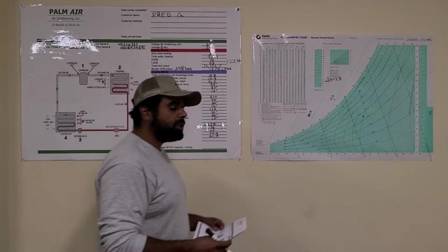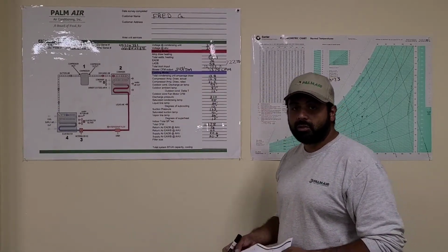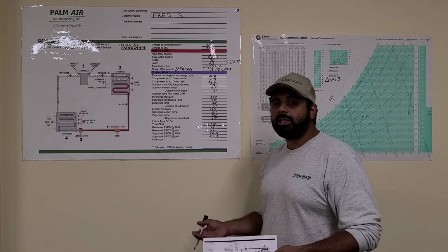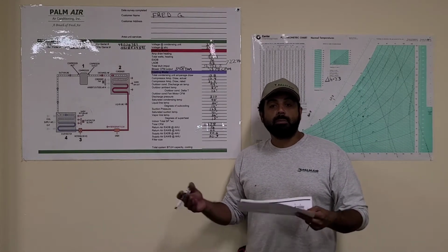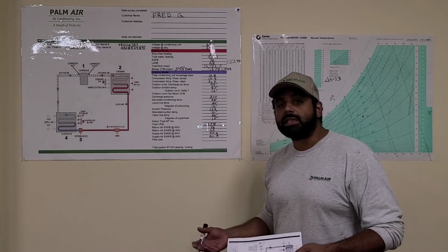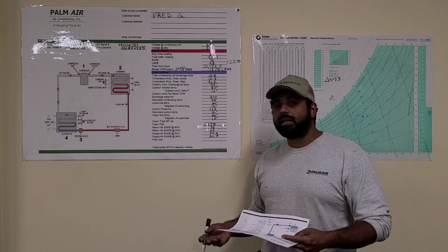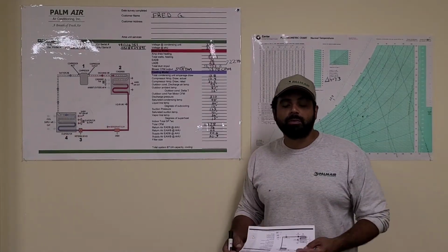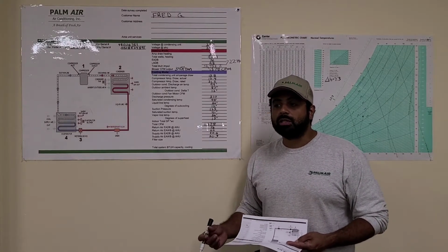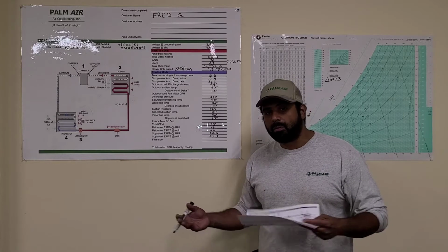Now, for those of you that aren't super familiar with air conditioning, there are two types of heat removed during the air conditioning process. Sensible heat, which is the number that we can see or sense, the number that we see on our thermostat. That's considered sensible heat. And then there's latent heat. Believe it or not, I get guys who chuckle when I say this, but latent heat is the amount of water that's being removed from the air. So literally, the water from your drain line is heat being removed from your air in the form of moisture.